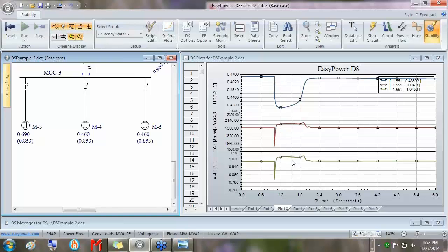Go ahead, do the best you can on gathering information and data. Yes, and put the data in all those other models for all the other motors so that when you're starting the one, you get the effect of all the others, because your voltage will go lower because of the dynamic effects of those other motors as they draw more current during the voltage depression.